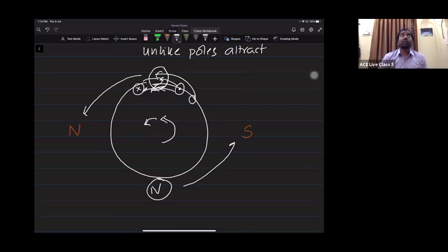Once this armature starts rotating, the positions of the conductors are changing. When the positions of the conductors are changing, then obviously the direction of currents in those conductors is changing. So because of the change of current from dot to cross, the same pole is reappearing in the same place. It looks like the same south pole is standing there. So this north pole is eagerly waiting for you to come and align. The armature is doing hard work to align, but the commutator is cheating, so that remains hope only. There is no chance that the south pole will get aligned with the north pole and this north pole with the south pole, and hence the armature will continuously rotate, rotate, rotate. Is this point clear?